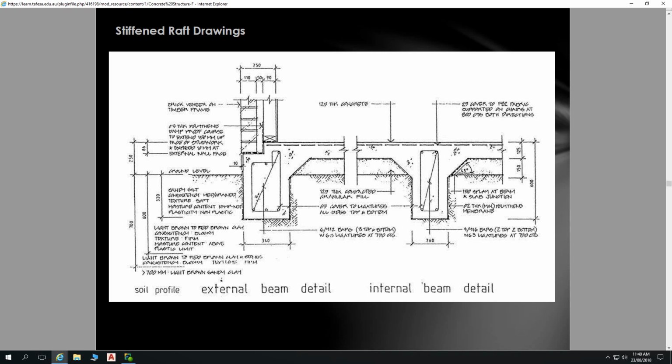If you have a lot of cement to a little amount of water, I'm just doing it in a nutshell. Don't apply this rule all the time, but in a nutshell, there's a simple explanation. A high cement to low water ratio will give you high strength concrete, but it will not give you much workability. So that concrete will not have much slump. You tip that bit of concrete out of your testing thing, it'll go like this.